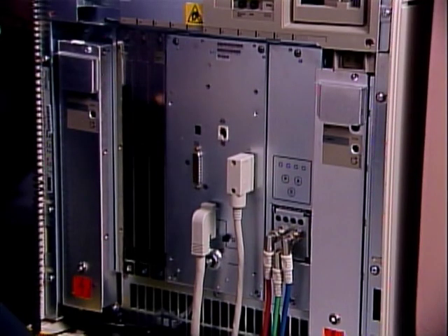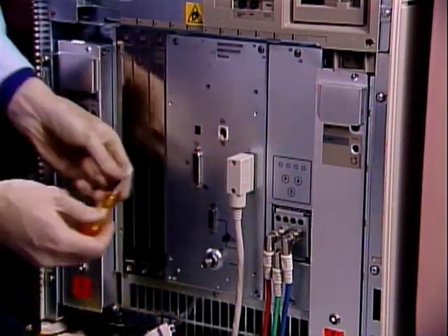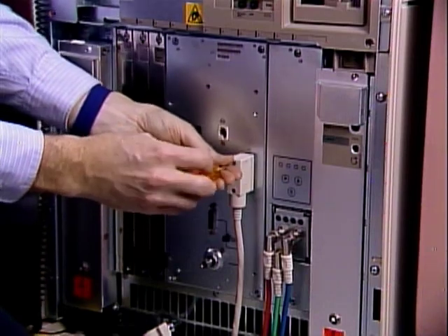To remove an M-bus module from slot 4 through 9, first remove the I/O cover assembly. Optionally, you may wish to remove any cables that are attached to the I/O cover. This is not necessary, but you may find it less cumbersome to work on the system with the cables out